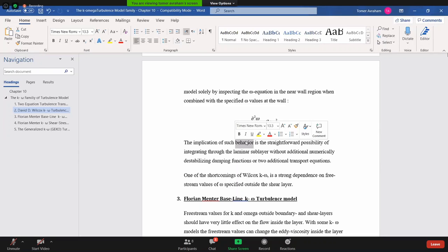So we can't really solve a lot of wall-bounded problems with LES. That's why I said in the beginning that combustion, where the flame is away from the wall, is gaining a lot of adoption because of the option to explore the turbulence content of the kinetics inside the flame.